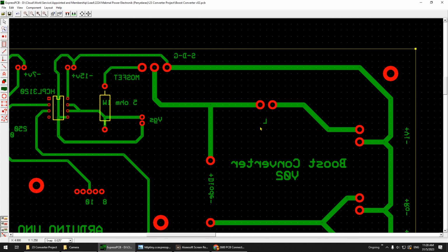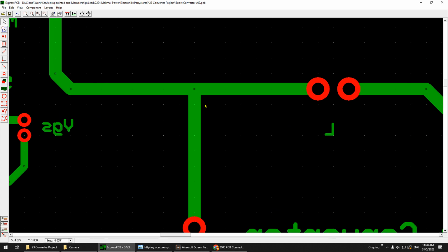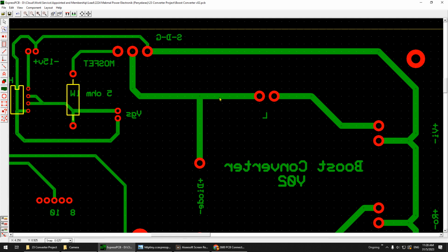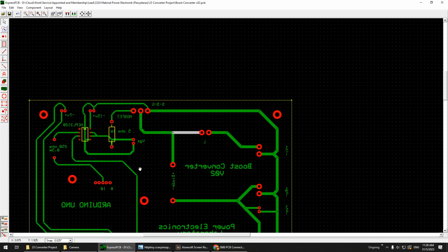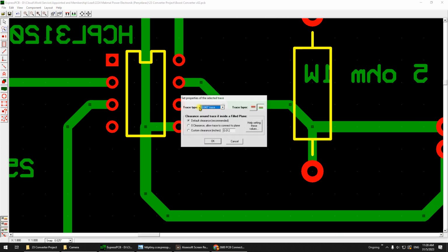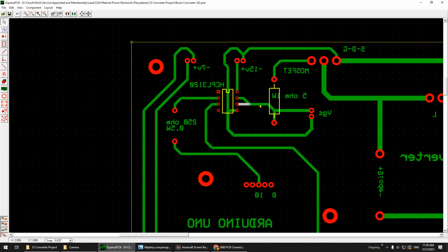Okay, because for UTM, for FKE UTM, if you want to use the heat transfer or printing method, you have to make sure that this line is thick. This one should be okay because it's quite thick. 0.08 is quite thick, but for this one it's not very good. When you do the heat transfer etching and so on, sometimes this one disconnected. That's why it needs to be large. Try to avoid small ones.